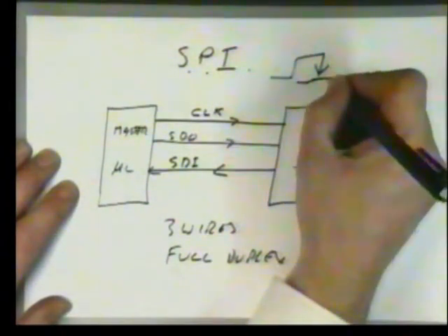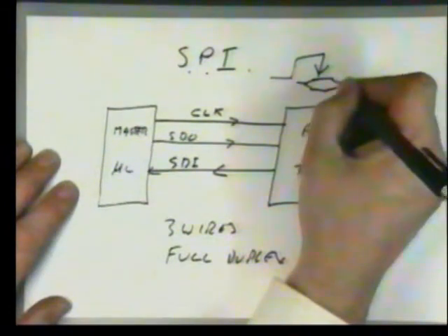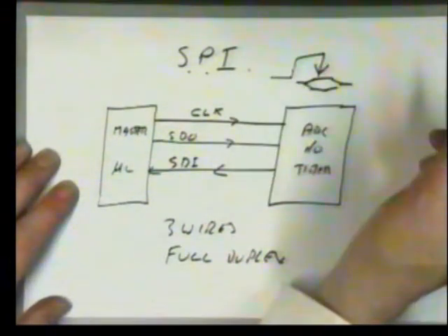That's when the data must be valid, but be wary of some systems do it on the rising edge. Data is always transferred in bytes, most significant bit first, bit 7 to bit 0. And don't forget, they're always out of phase with each other. There will be some redundancy.